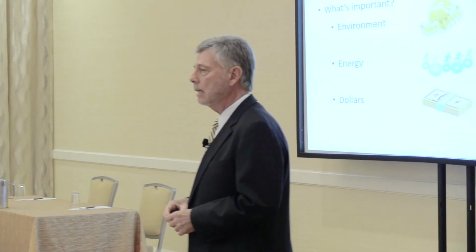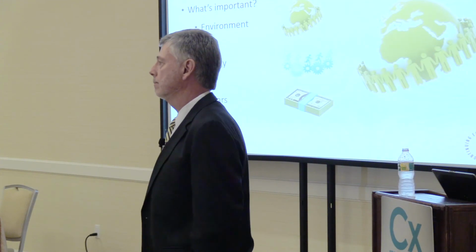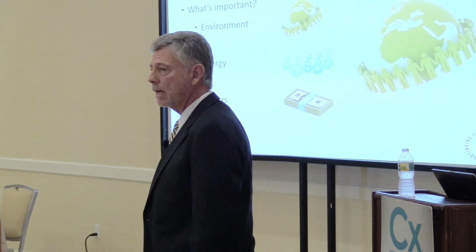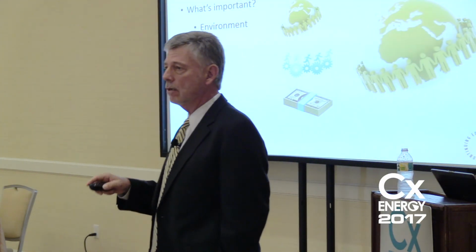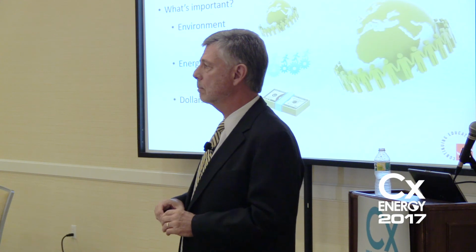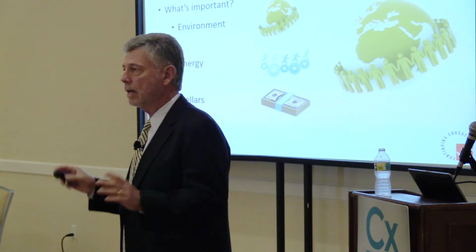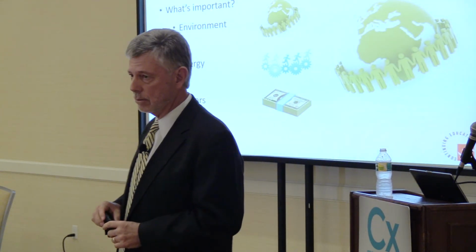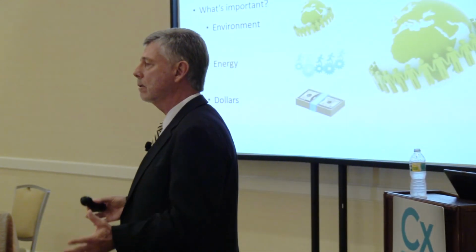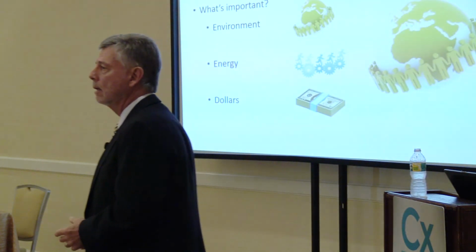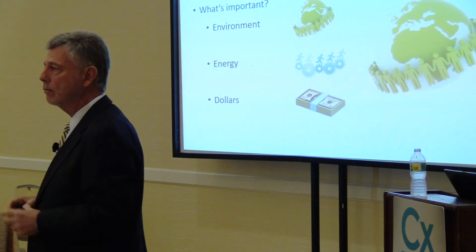And they delayed and delayed, and just last week they finally said, okay. So we hope we can turn that curve back around, but there are some specific things going on that we're very much aware of. We have told them, and I'm not trying to throw my client under the bus, but we pointed this out long before the energy began to go the wrong direction, that their airflow measuring stations needed maintenance. And if you're not measuring that air properly, you are controlling that fan improperly, and hence the increase in energy. That has a lot to do with that, whoever asked that question.